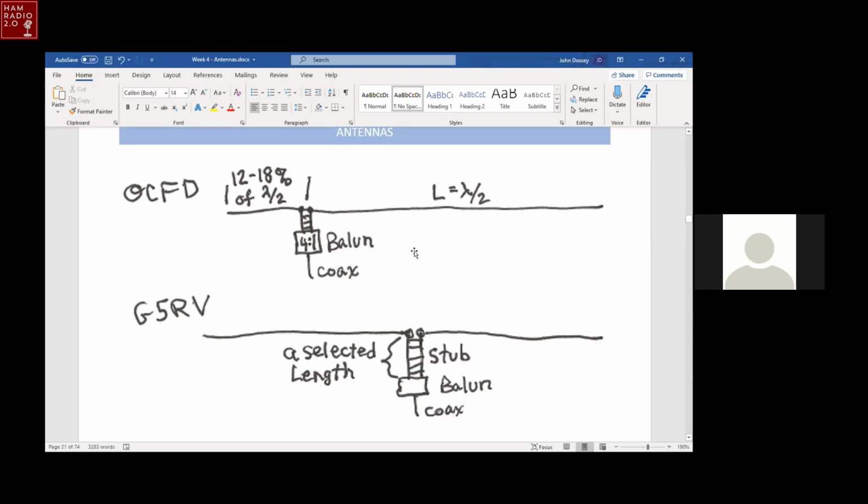Your off center fed dipole, that's a mistake there, right? On your balun there, there's supposed to be a gap where your 4-to-1 balun connects. Oh, you mean where I got the wire looks like it's joined? Yeah. Compared to the G5RV? Yes, you're correct. Okay, very good. Just wanted to make sure. Yes, thank you. If you short out the ladder line going up there, it's not going to do anything. That's what I thought. Just wanted to make sure for my own peace of mind.